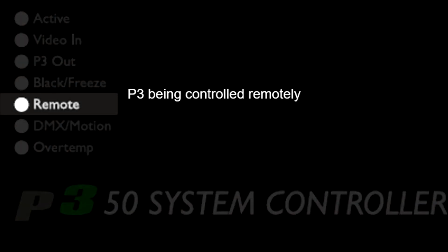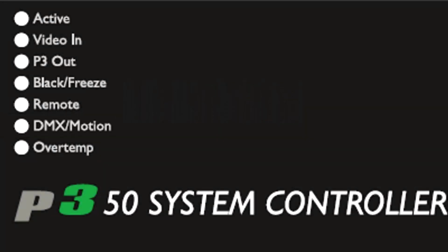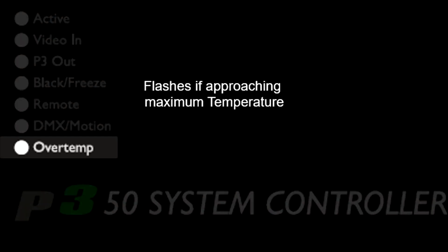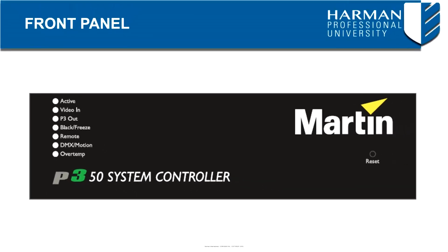Remote indicates that the P3 system controller is currently being controlled remotely by a P3 system manager or another P3 system controller. DMX motion lights when a valid DMX, either DMX or motion control signal, is present at the DMX or eDMX input connectors on the rear panel. Over temperature flashes if the P3 system controller is approaching maximum safe operating temperature. The over temperature lights constantly if it has exceeded this temperature. There is a thermal protection circuit which throttles down the processor if the temperature is exceeded.